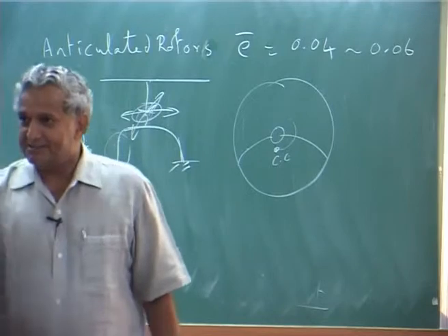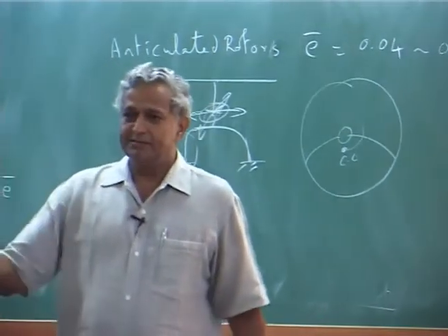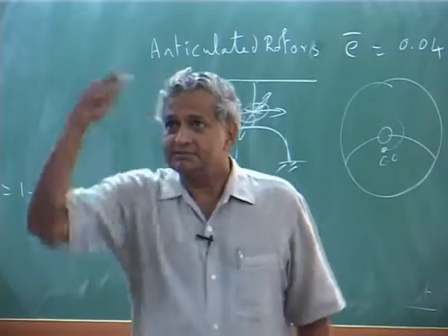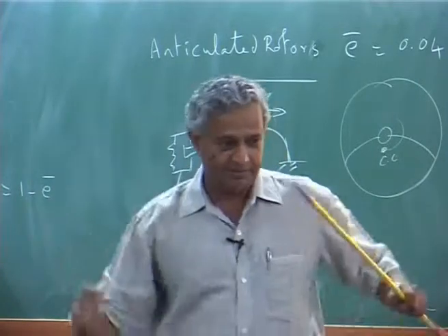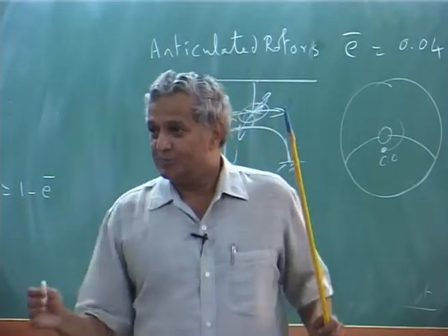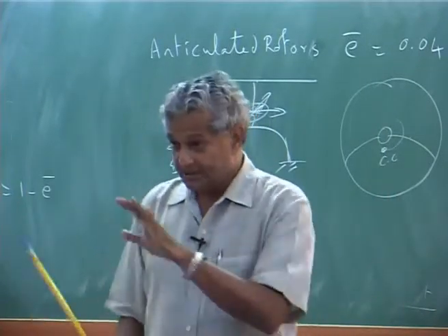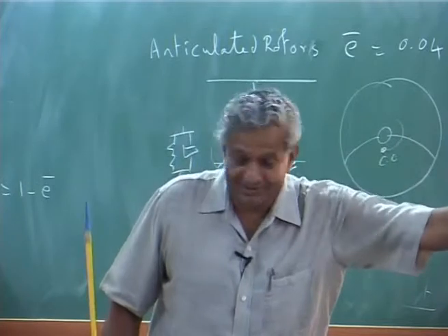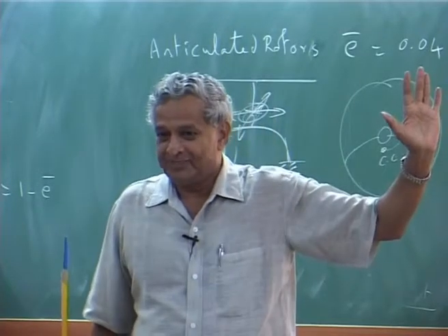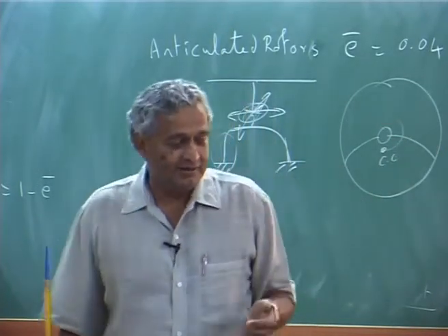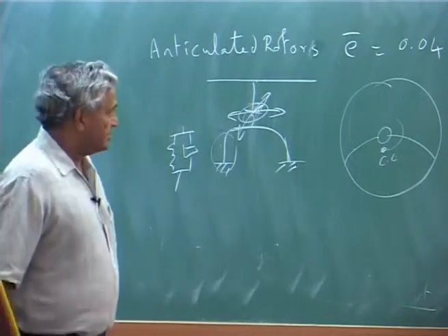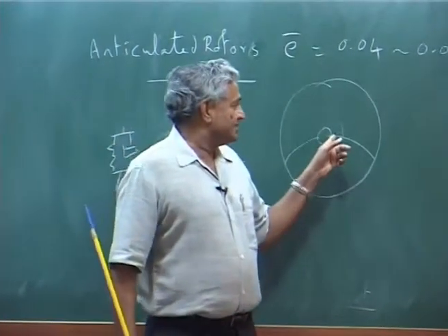That means it is giving an imbalance, an unbalanced mass going around, and that combines with the fuselage motion and it will start heavily oscillating. It is very catastrophic, because the moment the blade touches the ground, the blade is gone. In a teetering rotor, what they do is they make it stiff in plane.